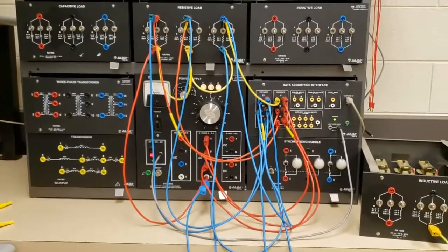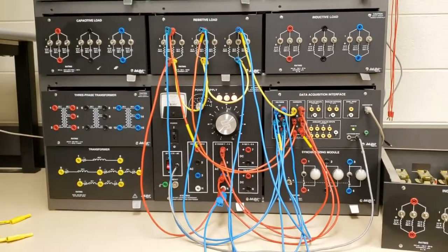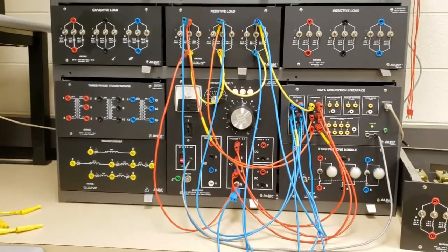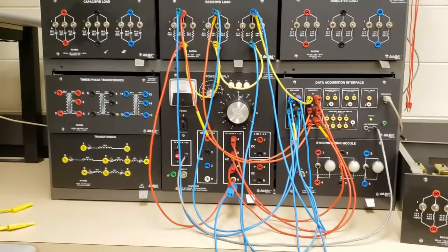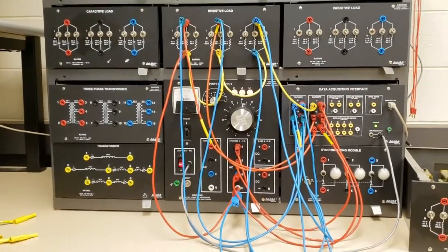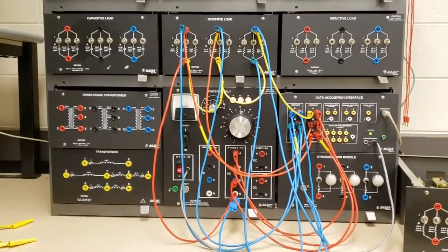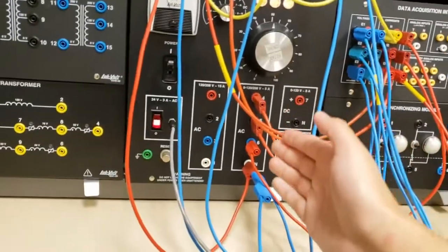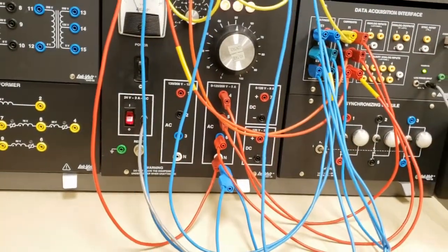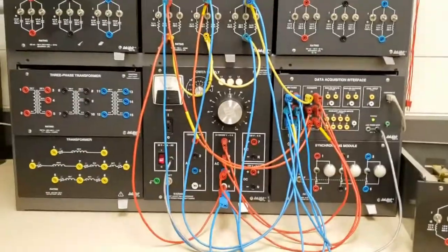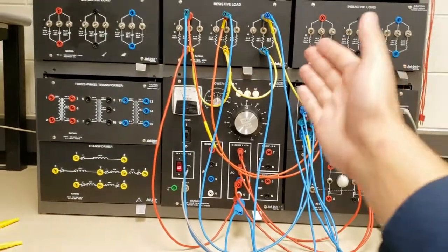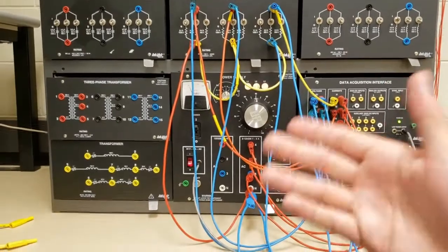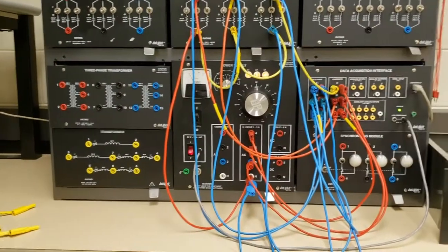Okay, guys, finally, this is part C of the lab. And this is where we finally build a 3-phase circuit, which is what you guys have been learning all about in class. It's the world of power systems, 3-phase circuit. All it is here is the simplest kind of 3-phase circuit. We're now using all of our terminals in the variable voltage supply. We set it at 60 volts like we have been. And we just have 3 resistive loads, 300 ohms on each line.